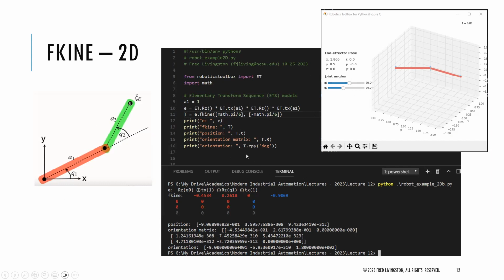And there is a Teach tool to allow you to visualize that, and you can actually move your joints here and you can see the location. And your roll, pitch, yaw is there. Certain systems do use quaternions, so you have to convert the roll, pitch and yaw to a Q vector, depending on your system. And some of these are in radians and some of these are in degrees. By default, this is in radians, and you can use math.degrees to go back and forth.